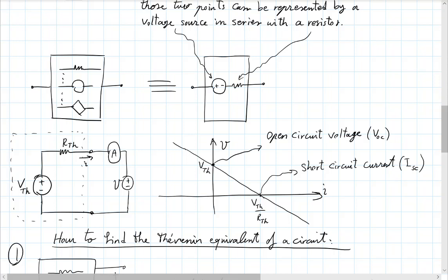R Thevenin, what does that mean for R Thevenin? So this point is going to infinity, basically, right? This line is going up. This point is shifting to infinity. Means R Thevenin has become 0. So V Thevenin over R Thevenin has become infinity, right? It's just a voltage source, 2 volts. So no matter what you connect to it from the outside, it will give you that flat 2 volts. Okay. So be careful with things like that.